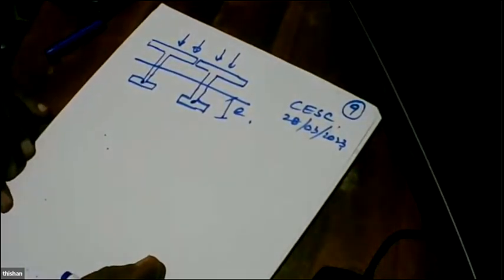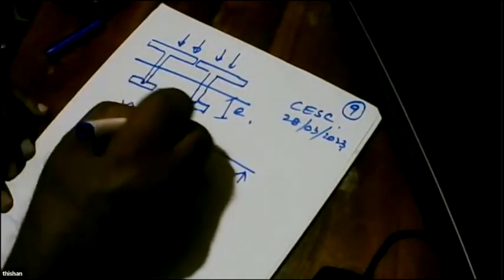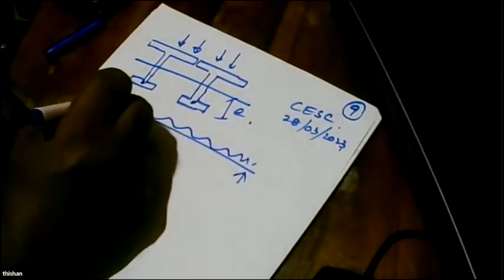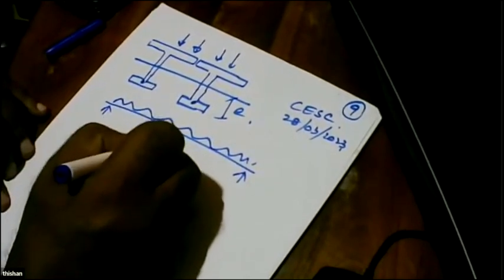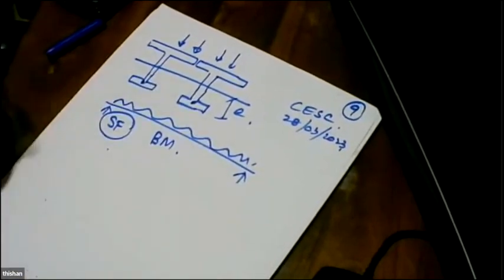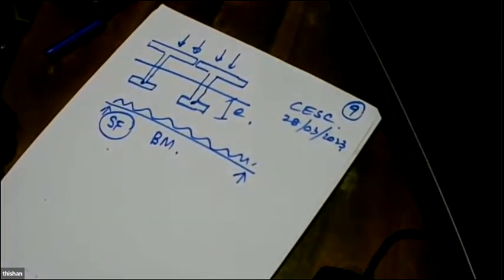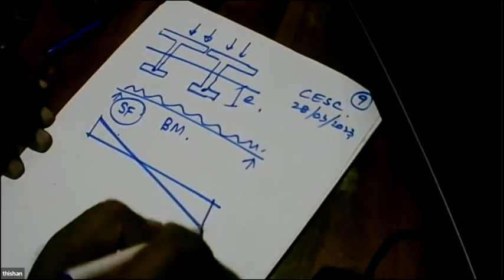And why we need a web is, when we have a beam subjected to flexion, you get a bending moment and a shear. To resist this shear, we like to have a web as well. But this web is a penalty in the central part because the shear force diagram is like this.